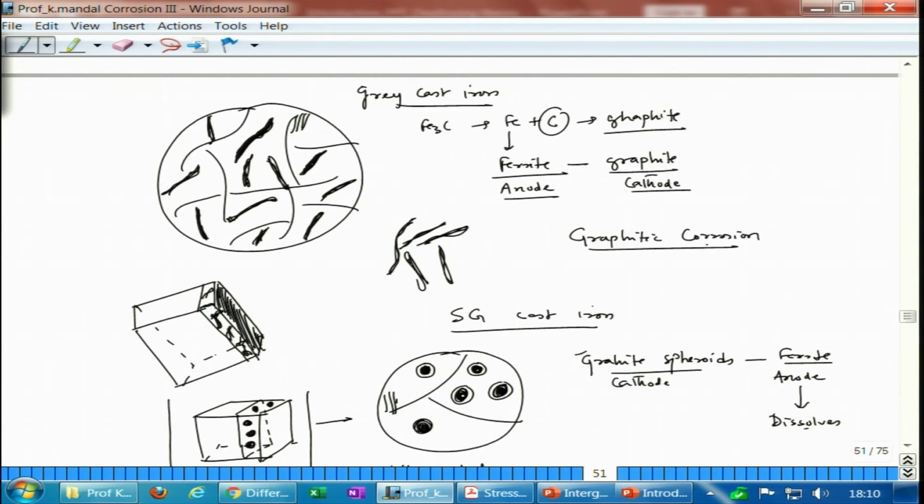So, this is also falling under the dealloying process, but here you see interestingly, in case of the zinc copper system, we could see that copper redeposits back. In case of the silver zinc system, silver redeposits back. In case of the copper gold silver system, you can go to the literature and search, silver dissolves, gold stays back. So, that is what you have, a fantastic network of pure gold porous structure.